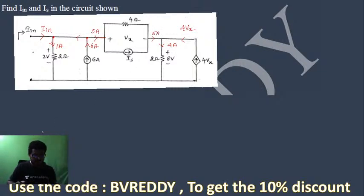Yes or no? Whatever the current here, some current may go here, some current here, but finally this must be 5 amperes only. This current is 5 amperes, isn't it? If this current is 5 amperes, then 4 amperes are going here, isn't it? Then how much current should go here? This current must be 1 ampere. Yes, that means 4 into Vx is equal to minus 1 ampere.